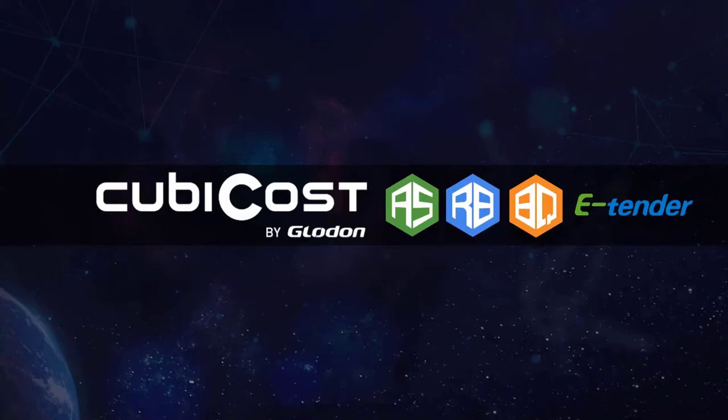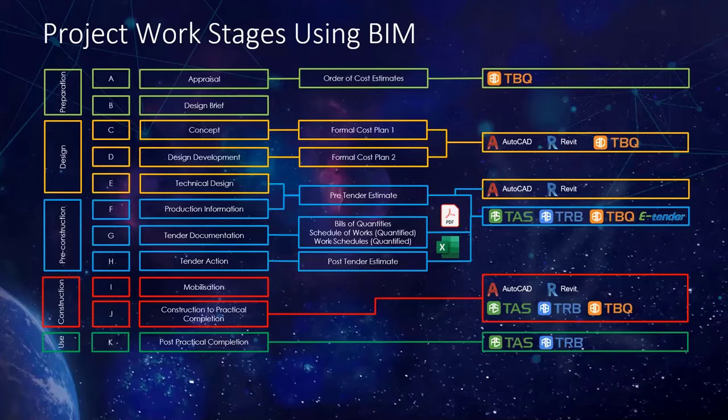In today's presentation, we're going to look into details of TAS, which is takeoff architecture and structure, and the TBQ in particular. BIM is utilized in different project work stages: preparation, design, pre-construction, and construction use. Different things are happening along the way. You have the first cost estimate, order of cost estimate, formal cost plan 1, 2, pre-tender estimate, and bill of quantities that you prepare at the pre-construction stage, and then you get into the tendering stage. At the same time, you're preparing the work schedules. Again, quantification is happening everywhere.